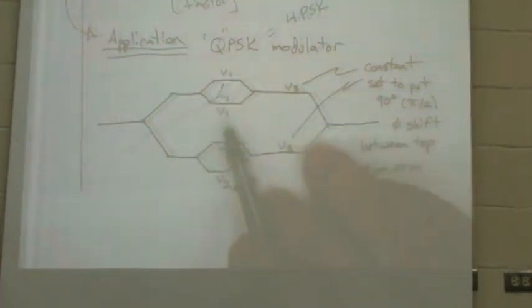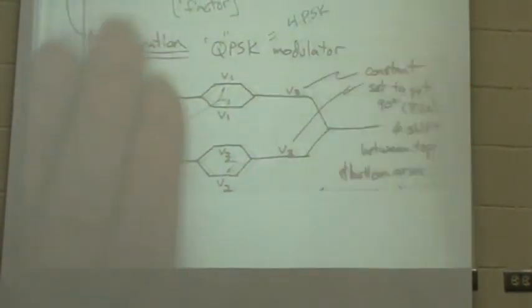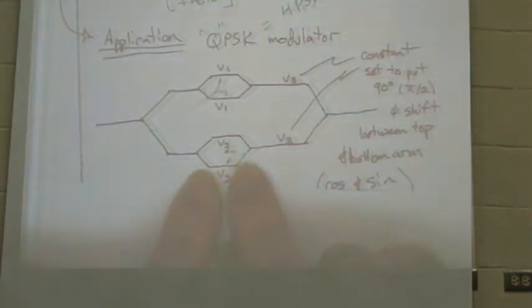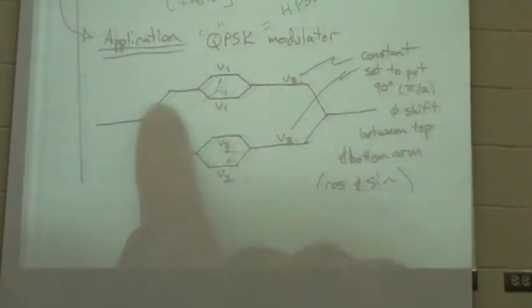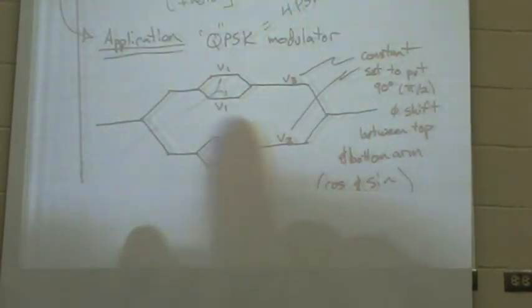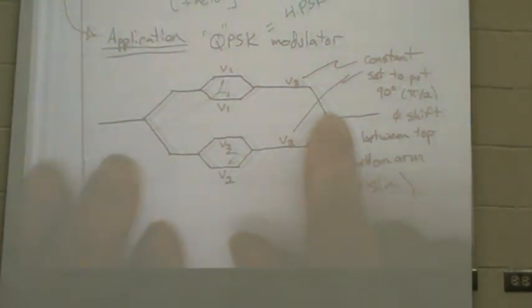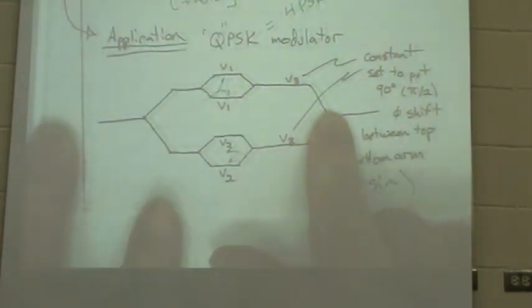Here's how you can build one of those. Have the device we were just talking about, an electro-optic modulator, make both voltages the same. Now that box is just a phase shifter, right? Bring in another one, right? And again, split the signal, go through this phase shift box, and then add the two back together. Aha. Then,